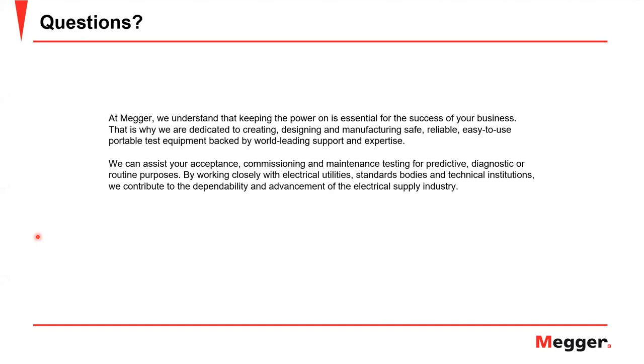Do you need a recloser system, or can the 79 element in a relay and breaker accomplish the same requirement? Yes, it is possible. In this setup, the breaker itself will be performing the tripping and reclosing action based on the currents that it is seeing in the circuit, and then the relay settings also for the 79 element. So the 79 logic in the relay will be monitoring the action of the breaker.